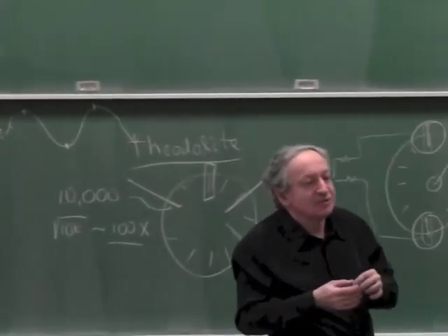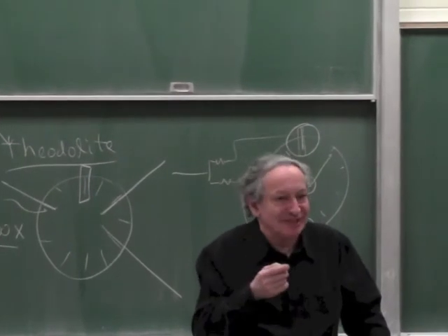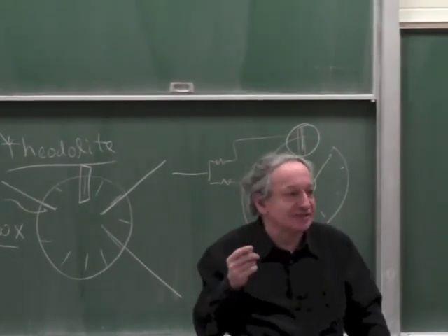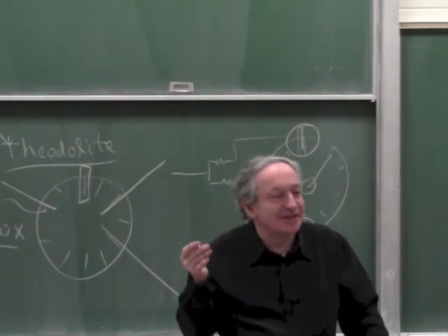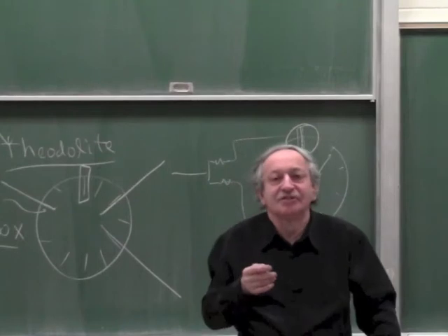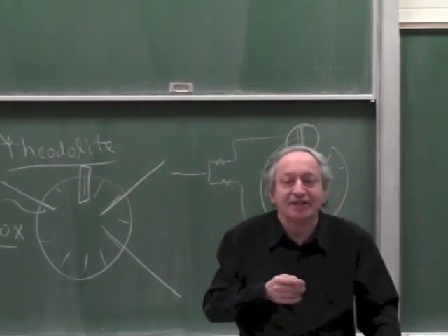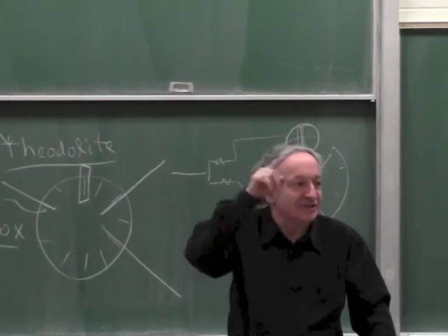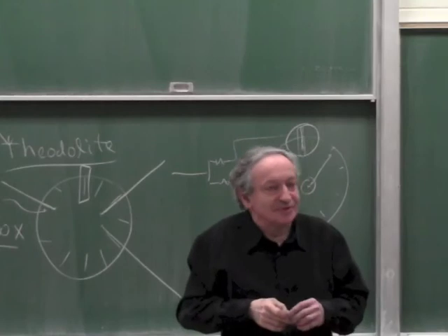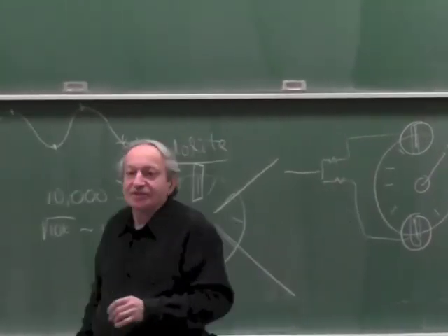It's basically not suitable to sense anything with information content of more than 15 Hertz. And even 15 Hertz is a limit, so let's say 10 Hertz. While a sensor which has a split detector and a light modulated at 100 kilohertz can easily pick up vibration of a few kilohertz and track it. Good, so that's a trade-off, but otherwise the camera is a very good sensor.